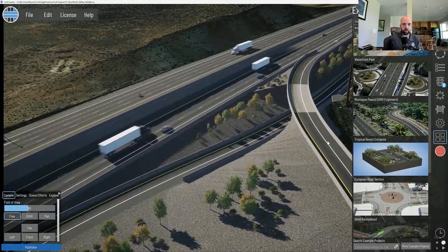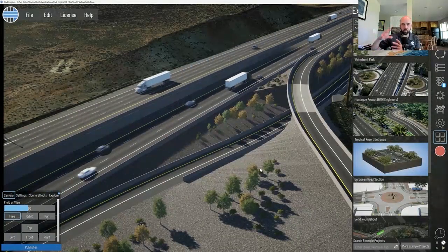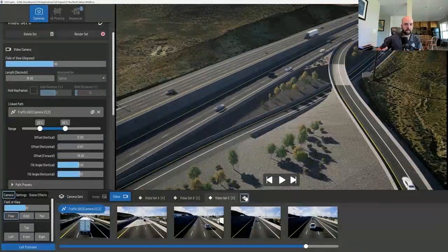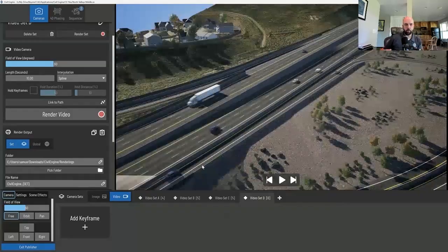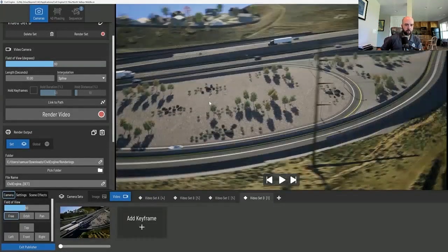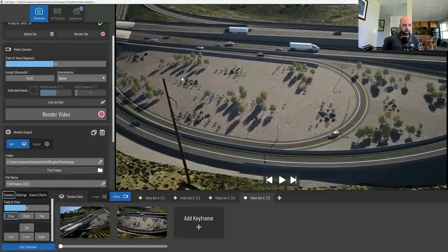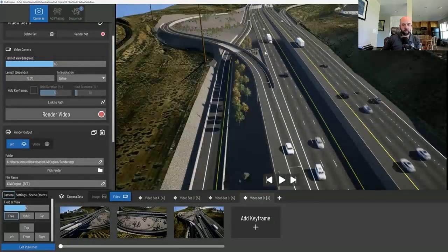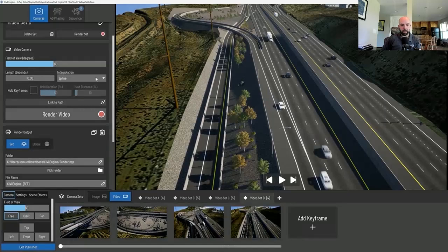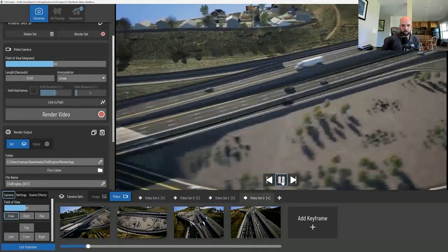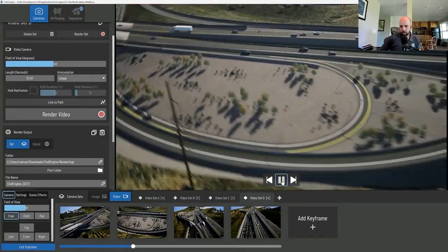You also have the option in Publisher to set keyframes, so you could potentially script the motion and rotation of that camera through the sky, and highlight or pick certain points through that project area to hit as it flies through. So if you're looking for some kind of fly-through rendering, this Publisher keyframing video render would probably be your solution for something like that.